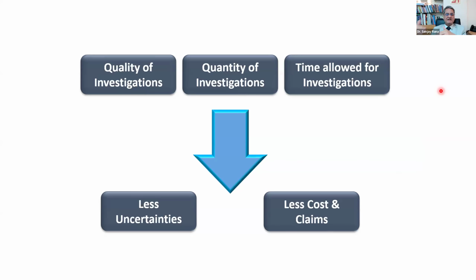First of all, it's low cost. Compared to any invasive method, geophysics is a very, very cheap method. Rapid coverage. You can cover hundreds and thousands of kilometers in a day, especially with the heliborne and airborne techniques which are available today. It gives you continuous information. That's the biggest point. Drilling gives you discrete information.